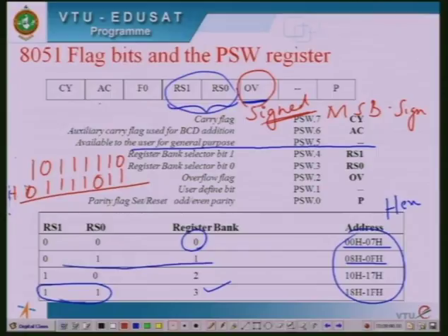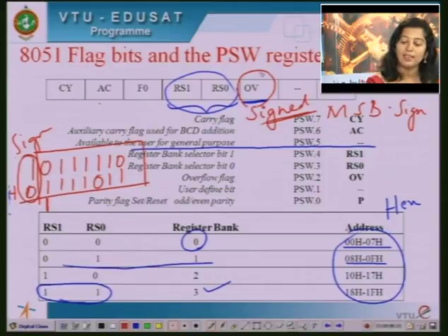When we perform any operation, we are going to consider only up to 7 bits. This will represent the sign bit and you should not consider this 8th bit. So, here 0 plus 1 is a 1 and there is nothing coming extra from here. That means the overflow flag will have a value 0.